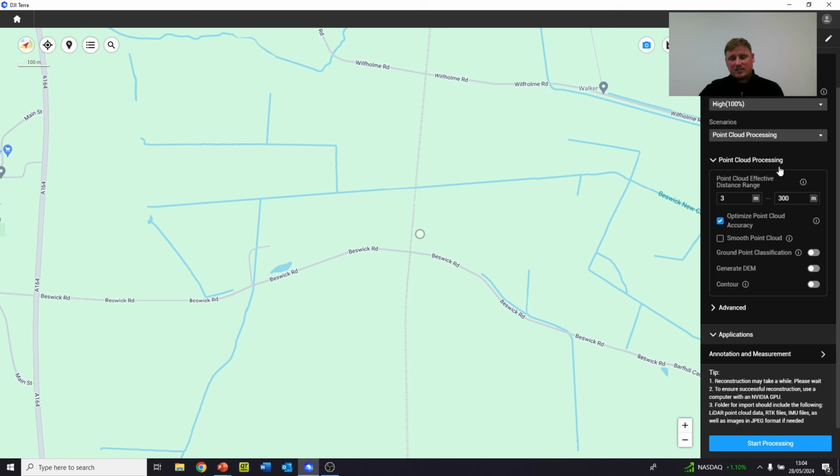Down in this point cloud processing toolbar, you can see there are only a few little boxes to tick and click. Now for that particular LiDAR sensor, I typically fly at around 55 meters. As when we're operating other laser scan systems, the further we move away from our LiDAR sensor, the more the data integrity is reduced. So if I'm flying at around 55 meters, I want to make sure the data I'm utilizing is within that high tolerance, highly accurate return range. So I changed this to 100. Anything outside that range is going to be removed and not used in the processing.